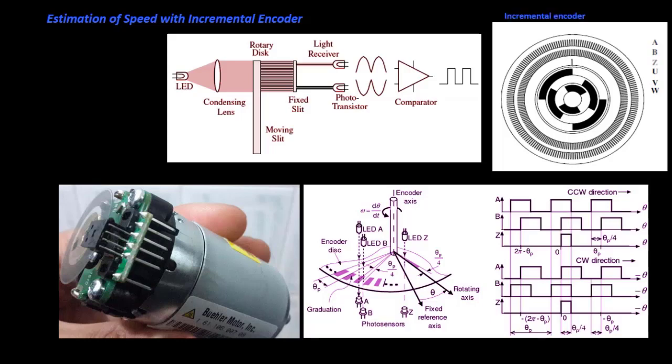To measure the speed or the position, the digital encoder is widely used, which generates pulse train, whose frequency is exactly proportional to the speed. The encoder can be classified as the incremental type, where the pulse corresponds to the relative position of the rotor, and the absolute type, where the pulse corresponds to the absolute position of the rotor. In particular, for the control of the DC machine or the induction machine, where the absolute position has no meaning for speed regulation, the incremental encoders are used without exception.